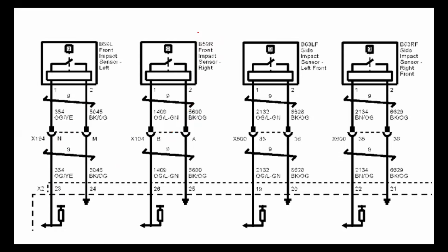Now, the reason we're doing this is when I go in and look at the service manual procedure for testing these circuits, they basically have you run some continuity tests on the wire to make sure the wiring is intact. And if the wiring's intact, then basically you are to replace the sensor. Both of these sensors that are setting codes are brand new. So we know that that's kind of a false trail. So I decided to sort of go over and above what the service manual will tell you to do here and just kind of test it my own way.